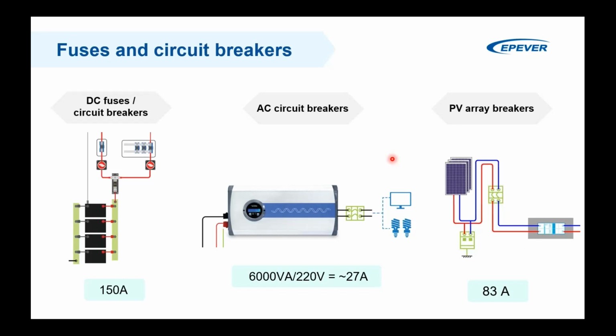Otherwise, you are at big risk. If you short circuit the cables with the negative terminals during the maintenance process, and you do not have a smart battery protector, it's not good. The parts will be damaged. So we normally use the isolators.